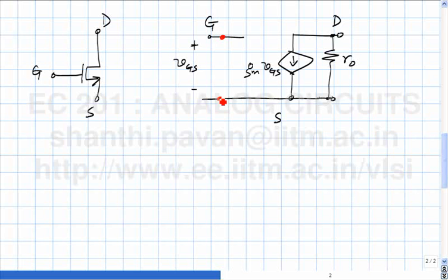As a network theorist, one thing you can be sure of is that any two nodes will have capacitance between them. So it turns out that the incremental input impedance of the MOSFET between the gate and source, while it's open circuit for DC, has a capacitance CGS between gate and source. There is also a capacitance between the drain and gate. So this is CGD, and it turns out the way the MOSFET is constructed,